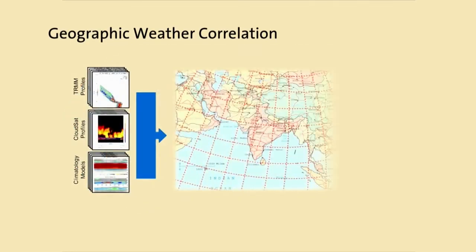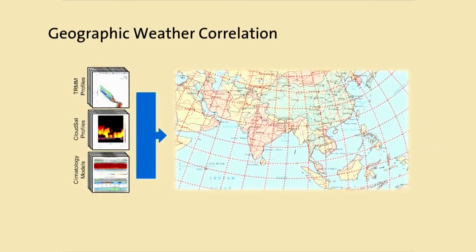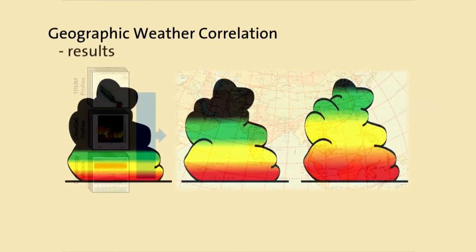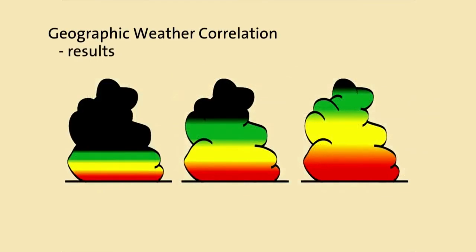MultiScan incorporates these weather models into a worldwide database that resides inside the radar. Using a 10-degree by 10-degree geographic grid, the radar sets thresholds based on geographic position, time of year, and whether the aircraft is over land or water. In regions where thunderstorms exhibit very poor reflectivity characteristics, thresholds are set low so that when the radar detects moisture at lower altitudes, it can predict that the cell top reaches to the aircraft altitude.